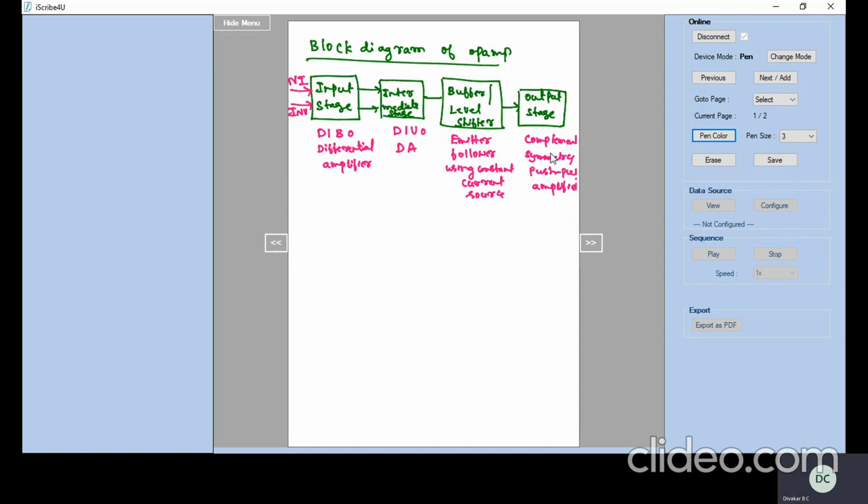The second one is the differential input mode. In this double-ended differential mode, two opposite polarity signals are applied to the inputs. And the common mode operation is, in the common mode, two signal voltages of the same frequency and amplitude are applied to both inputs. They tend to cancel, resulting in a zero output voltage.